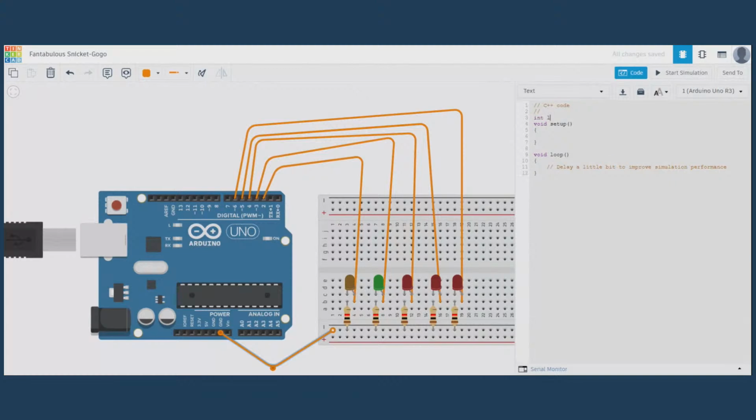I'm going to keep each LED a different name. You should not give the same variable for all the LEDs. If you do, the program will get confused. It doesn't know when you turn on the first LED, the second LED by its own. We should give clear information to the machine to perform the work as you wish. int LED1 equals 2. First LED is on pin number 2. int LED2 equals 3.